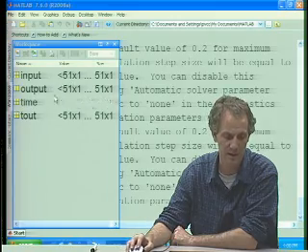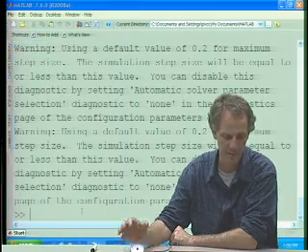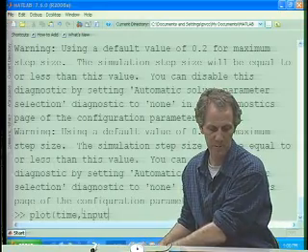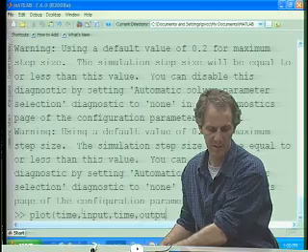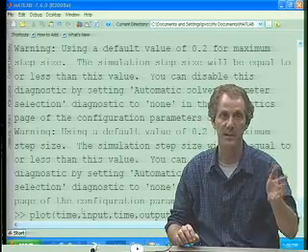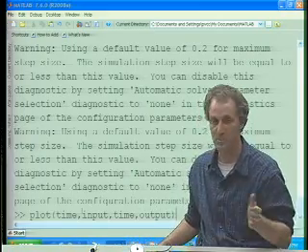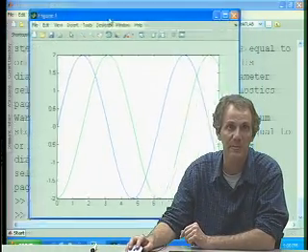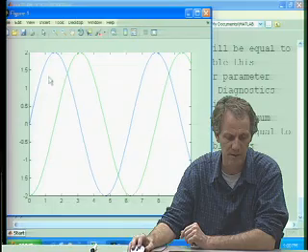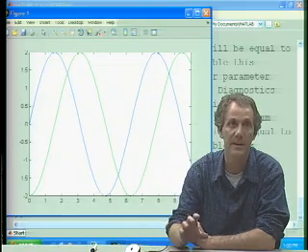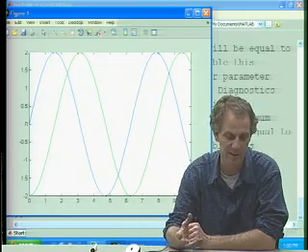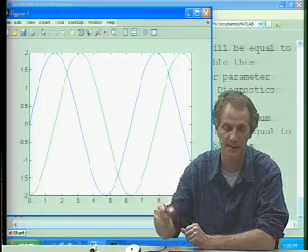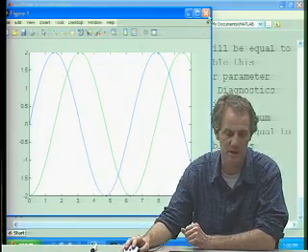And so those are new. Those were just created by Simulink. And for instance, I could then say plot, time, comma, input, comma, time, comma, output. The syntax there is x, y, x, y. x1, y1, x2, y2. And now we see 2 plots pop up. The first one is the sine function, and then 90 degrees out of phase from that is the integration of it, negative cosine of time. So it's sine t and negative cosine t that we're seeing plotted there.